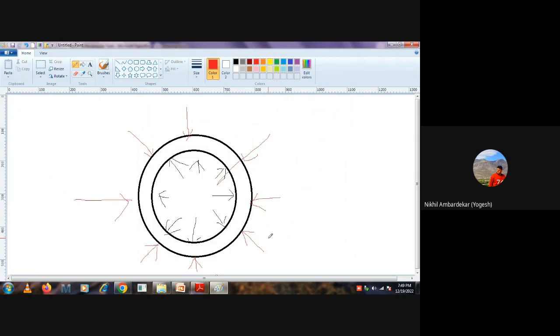Correct. So these are the basic reactions that happen with respect to different types of pressure. If the wall is subjected to internal water pressure, tension will be generated in the wall. As against that, if we consider the soil load from the outside face of the wall, compression will be developed in the wall.